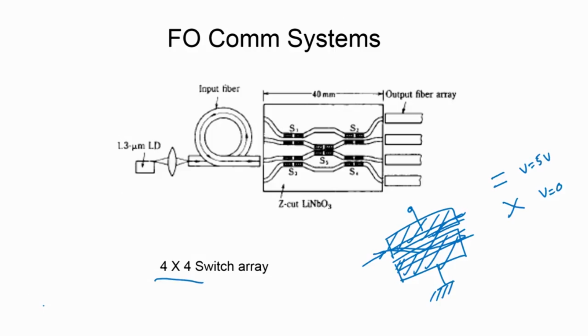There is one additional feature which we have not discussed earlier, which is that there are tapered regions. These directional couplers have to be tapered if you want to connect inputs and outputs. Of course, there is a tapering between these sections which we are ignoring at this moment for conceptual purposes, but in a practical situation we need to consider the coupling of light between these and then adjust the voltages or the coupling lengths accordingly. For the time being we will assume that the functioning of these directional coupler switches is as discussed earlier.